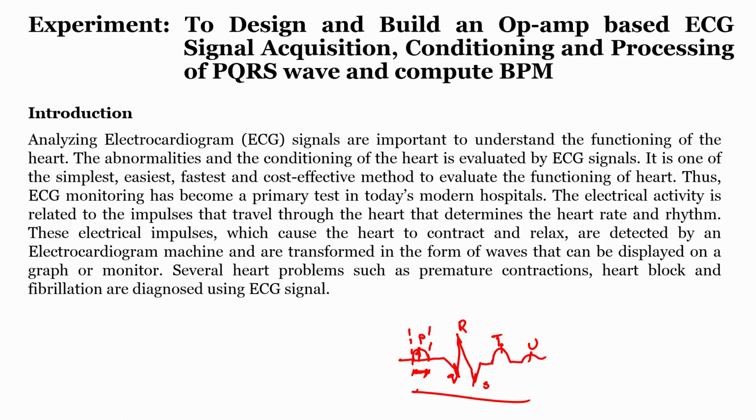So, how can you do that? If I use a half wave rectifier, it can only allow the positive signal, and it will suppress the negative signal. As a result, I can only see positive peaks here, something like this. So, this is nothing but our QRS, wait, again we will draw.